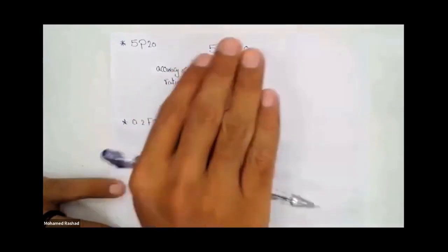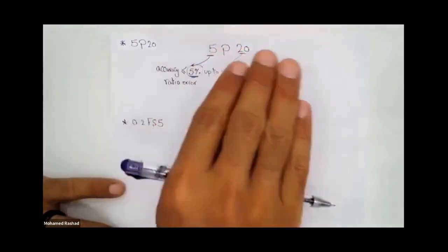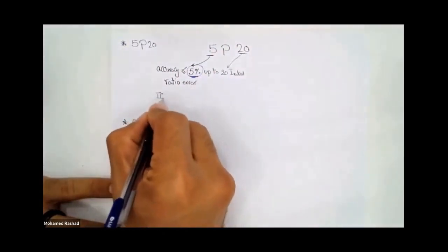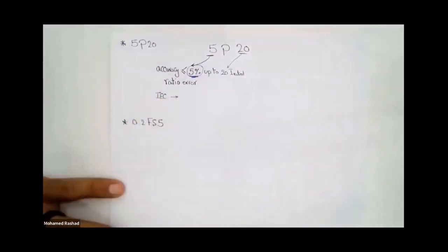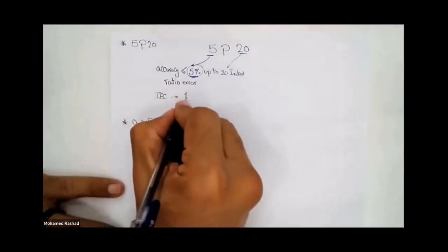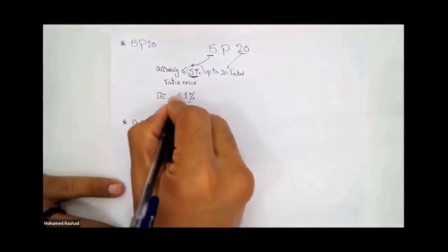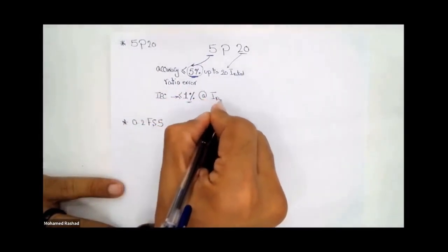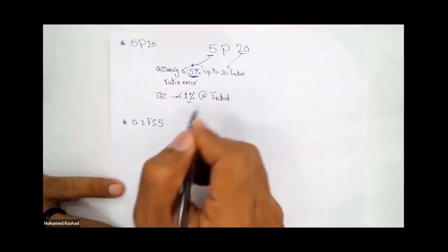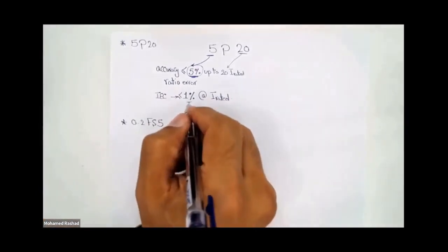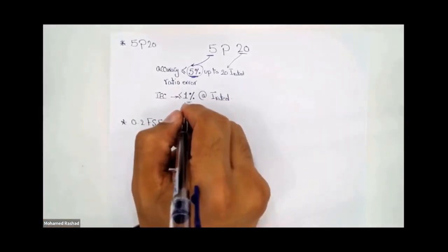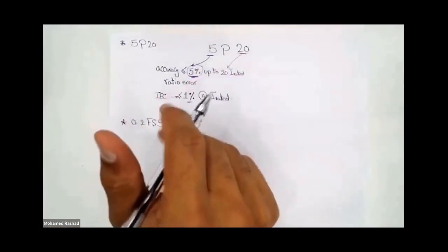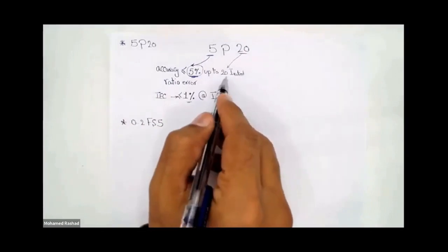So, engineer, if I am now operating at a normal current, the full load current, well, according to the IEC, which is the standard upon which this CT is based, the error ratio should not exceed 1%. This is at the rated current. It follows the 5% rule as long as the current is greater than the rated and less than 20 times the rated.